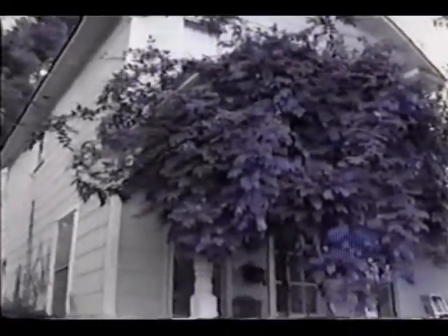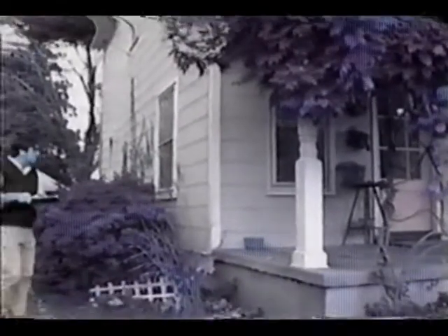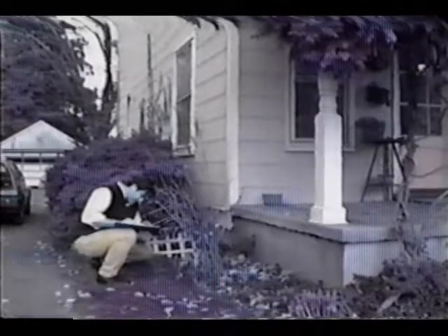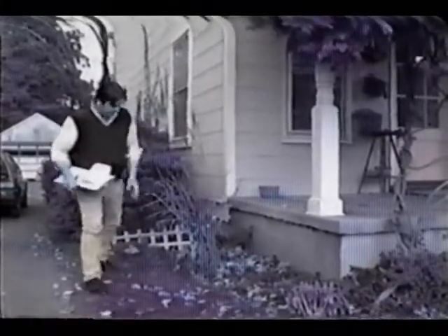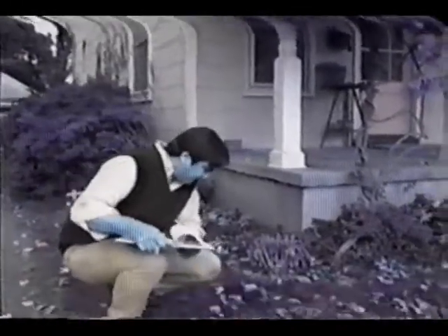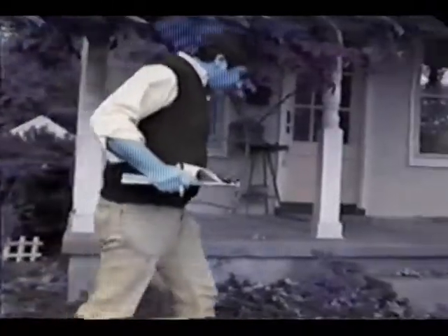The sampling procedure begins by determining the locations where the core samples will be taken. Start with the area around the perimeter of the building. You will be collecting between 3 and 10 subsamples from all sides of the structure where bare soil is present. Look for bare patches of soil near the foundation of the structure. Allow about 2 to 6 feet between each subsample. Mark the subsample locations on the property sketch.